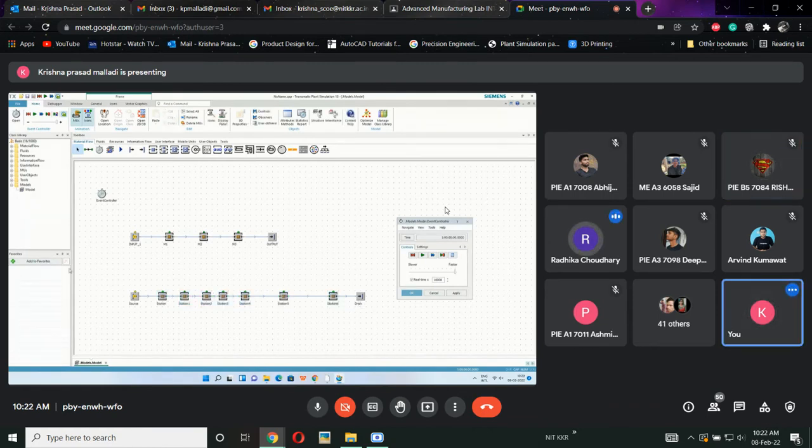Fine. Now, sir, for example, if you want to create two products which take different times, we will have to create a different frame for each product. As of now, no need. If it is a single plant, and you are preparing a larger model like I told you in yesterday's session, with 10, 12 or 20 processes, and you want to differentiate, then you can use different frames. Otherwise you can create it here itself.